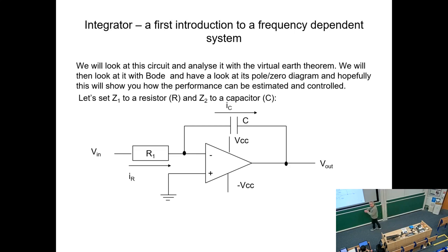Because at DC, so just go to extremes, at DC, a capacitor is 2 plates and is an open circuit. Nothing gets through. There's no way through. So we have no feedback from output to input with a capacitor there at DC because the circuit is broken. Okay? So this is effectively now an open-loop system because whatever happens here cannot affect the input. Therefore, it has no control over keeping this virtual ground in place. Open loop now. And, you know, that's not what we probably want. Maybe we do, I don't know.